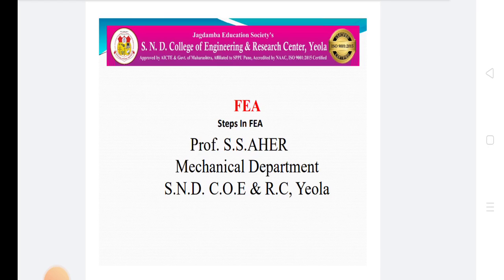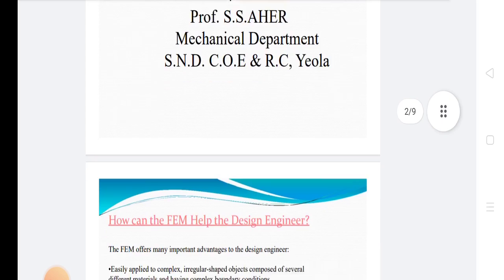In the general FEM procedure, the solution of a general continuum problem by the finite element method follows an orderly step-by-step procedure with reference to the static structural problem. The step-by-step procedure is: in the first step, discretize the given continuum. Step 2, selection of displacement model. Step 3 is the derivation of element matrices and load vectors. Step 4 is assembly of elemental equations to obtain global equilibrium equations. And step 6 is to determine the unknown parameters. So today we discuss these steps one by one.